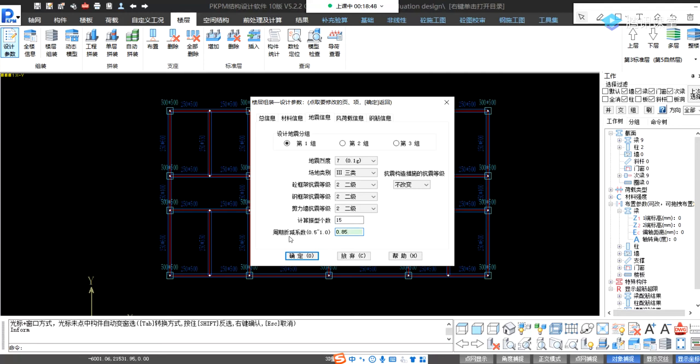Okay, and here this is the reduction coefficient about the structural period, the fundamental period. For a frame structure, the default value maybe is 1. And for our frame structure, commonly we input 0.85 here. Okay, this is all the information for the seismic node.